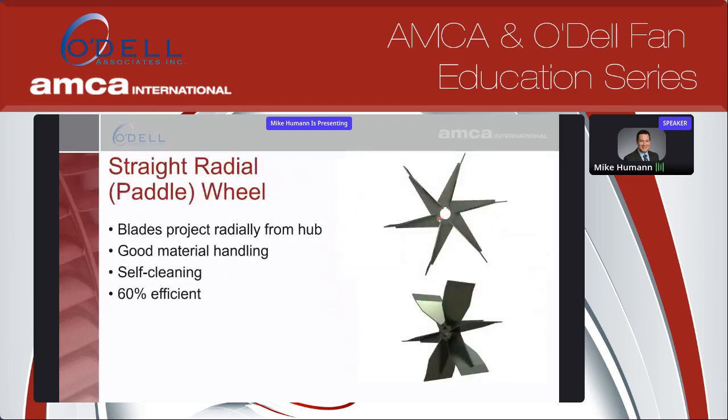We talked about the blades extending radially out from the hub. You can see here in these pictures, this is a paddle style wheel. This is one of the oldest designs of fan wheels. It's very blunt and tends to not be very efficient, but it is good for certain applications where you're handling material or handling some heavy dust loads, and they're also self-cleaning. It's hard for material to stick to the front sides of these blades as it's rotating.